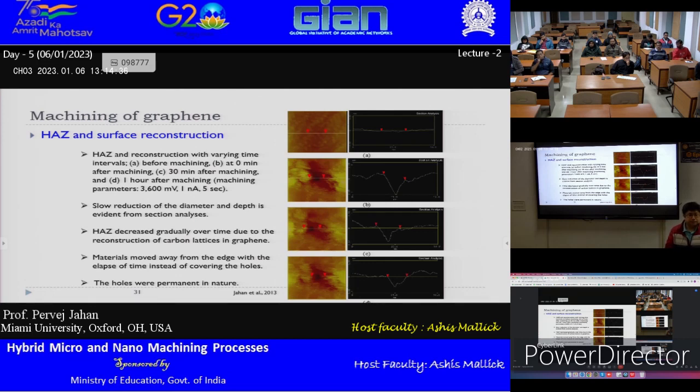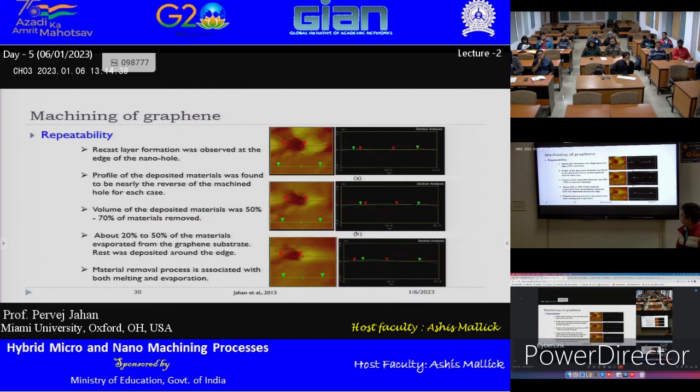How do you confirm that that's a recast layer? So that's a very good question. So I think in most of the cases from here, when there is a color change, that also indicates some kind of phase change on the surface. So I think from there we are able to get that information. But I remember that we were also able to collect some other information in those zones. Yeah. So that tells you that there is some change in that material compared to the parent material.